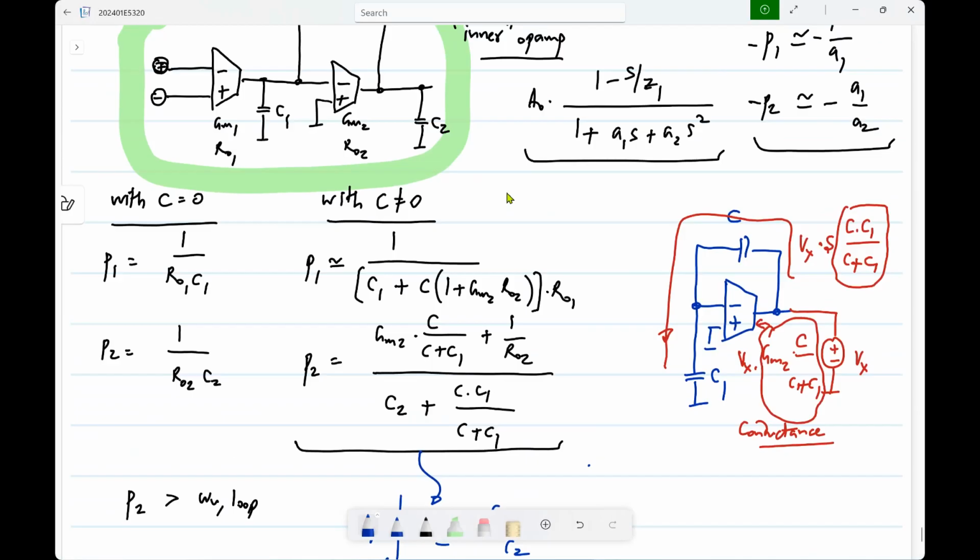And of course, every circuit comes with its opposite polarity counterpart. Whatever you can do with NMOS, you can do with PMOS and so on. So the number of transistor level circuits can be a lot. But if you understand it at this level, when you see the transistor level circuit, you should be able to sort of mentally classify it into one of these things and then see what's really going on. As we already said, the first stage is this GM1, it tends to be a differential pair because you want to have a difference input in the general case and so on.